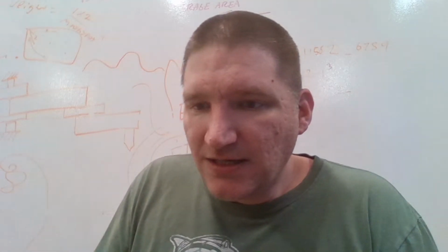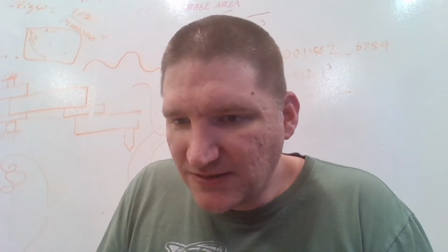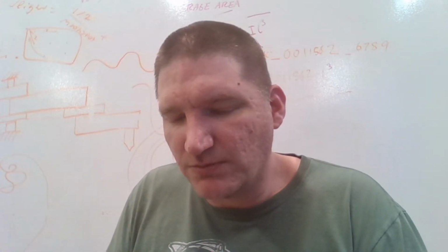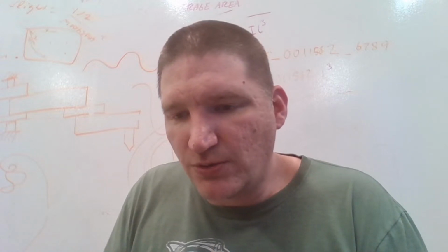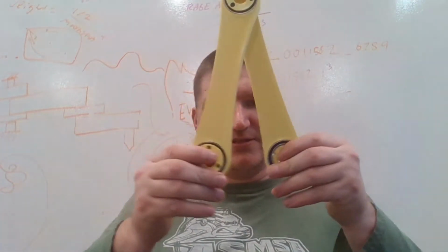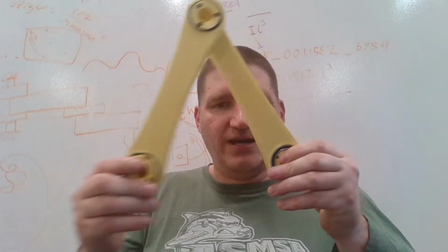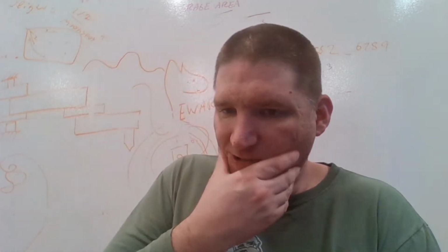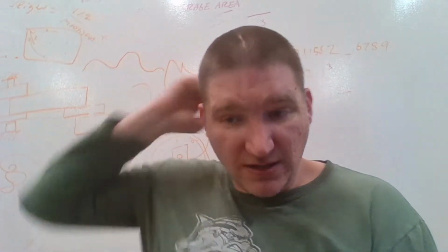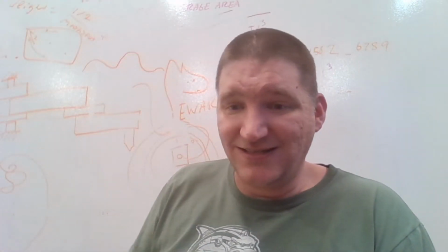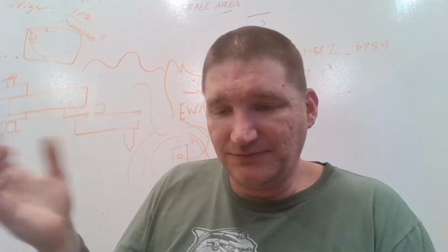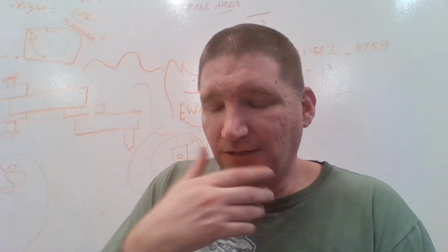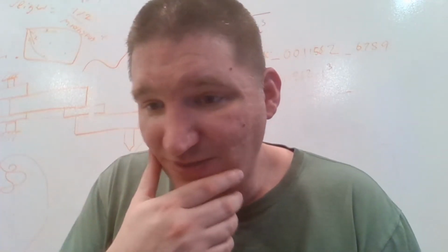Since each arm is a constant length, you could run a pulley system along an arm to make a direct drive printer with remote extruder motors. Oh yeah, somebody made a Prusa that had arms essentially like this with belts that go along it and then drove the extruder. So you could just use the arms that are already going there to do a direct drive. I'm not going to do that. The orbiter is so light that there's no need. And I think all the weight to do that might be close to the weight of the orbiter. They're amazing. At least I haven't got one. Everybody that has one says they're amazing, so I'm going to go with that.